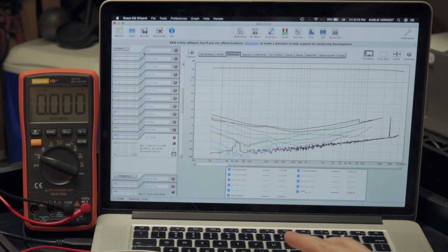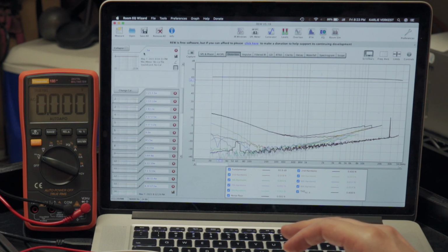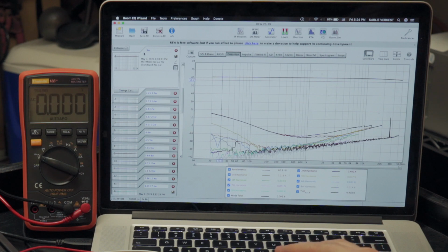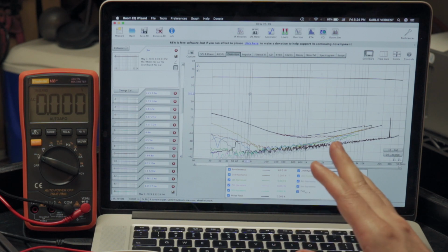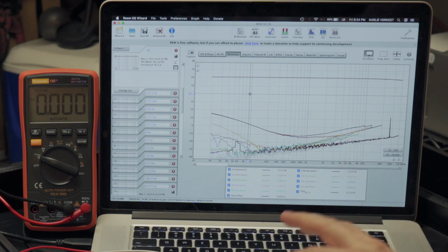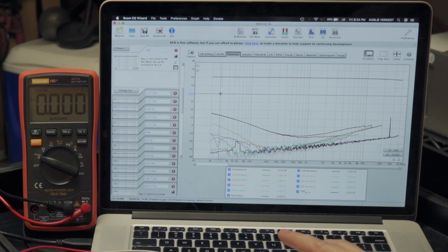And so it's interesting. The amplifiers that I build have limited negative feedback, and they have a tendency to have their distortion be lowest at low powers and gradually climb as you approach clipping, whereas this amplifier, which I think is actually more typical of a solid state, high loop negative feedback amplifier, has its highest percentage of distortion at its lowest power levels, which can be problematic actually because most of your listening happens at a couple of watts, right? And so to have that also be the point where the distortion is highest could lead to a bad listening experience, potentially.